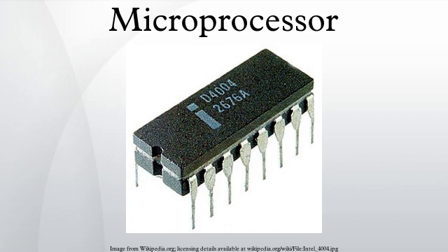The CDP-1802 was used because it could be run at very low power, and because a variant was available fabricated using a special production process, silicon on sapphire, which provided much better protection against cosmic radiation and electrostatic discharge than that of any other processor of the era. Thus, the SOS version of the 1802 was said to be the first radiation-hardened microprocessor.